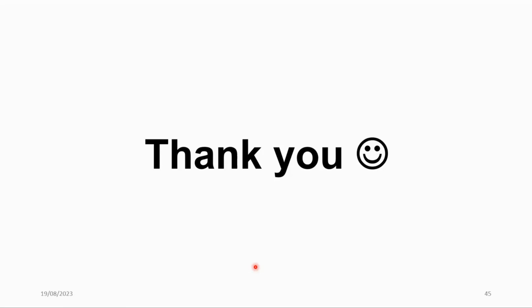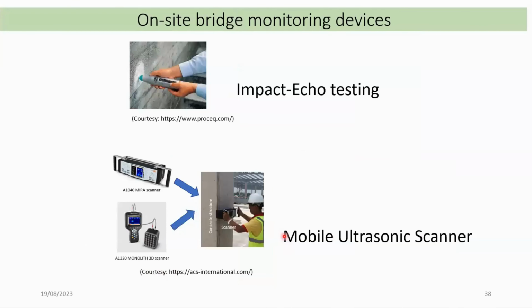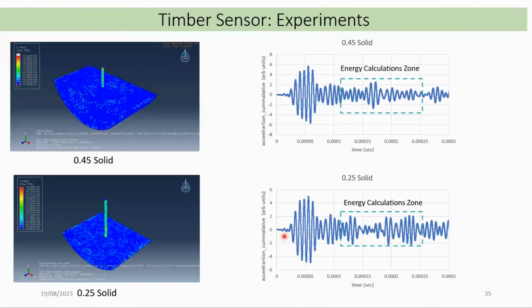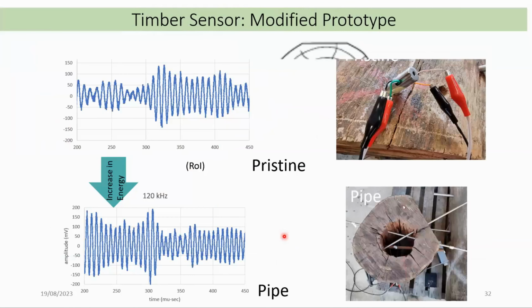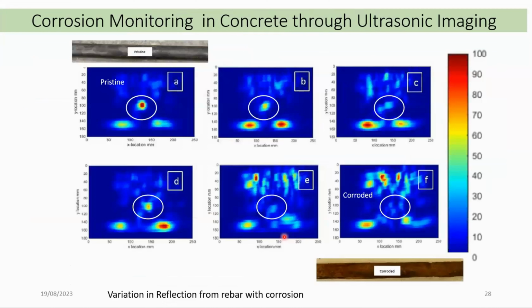Thank you, Hiran, for this wonderful question. When it comes to drone inspection, maybe I will go back to one slide, this one. Okay. With drone inspection, it is mostly visual inspection. Unless the damage shows up on the surface, we are unable to pick up information about the damage. In the case of corrosion, as we have seen, unless the corrosion progresses to a very advanced stage, there are no signs of damage.